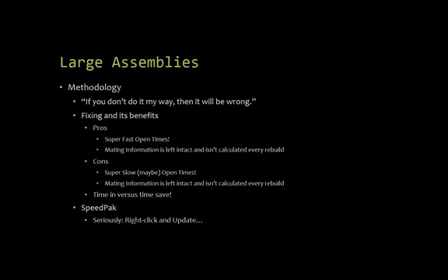That just seemed real weird to me. So as I was looking at it, I realized, well, hey, with this fixed relationship, I'm suppressing the mates. The mates are still in the assembly, but they're not part of the calculations anymore. So now my rebuild times are going to speed up and stuff like that.